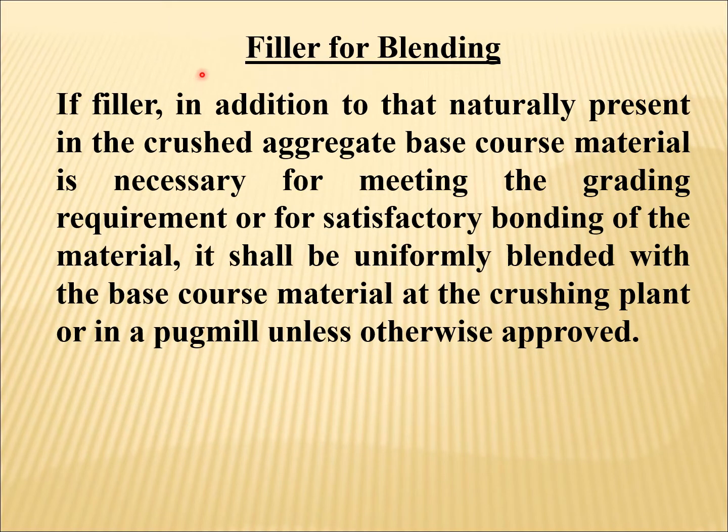Okay, now look at filler or filler for blending. A filler, in addition to that naturally present in the crushed aggregate base course material, is necessary for meeting the grading requirements or for satisfactory bonding of the material. It shall be uniformly blended with the base course material at the crushing plant or in a pug mill unless otherwise approved.